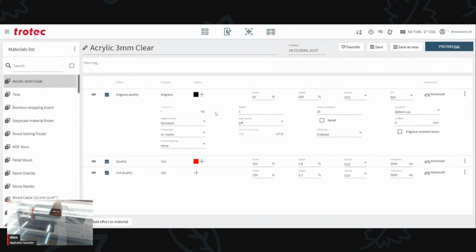Then the other setting under here, depending on the type of laser you have, not so much needed on this one, is the type of pattern. We can very easily automate dot patterns in here by using the ordered pattern function and using a grayscale graphic. That's widely used for edge-lit acrylic and plastics.